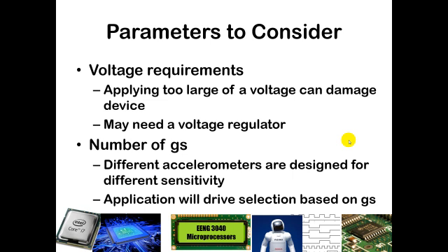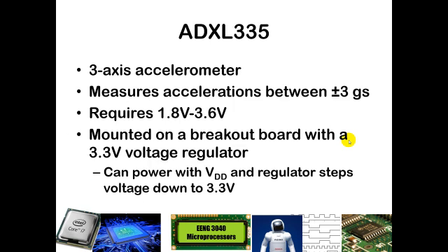If you are just trying to put an accelerometer into a tablet and may just reorient it, or perhaps you're trying to measure steps in a step counter, you don't need very high G ratings in order to do that. And so the application will determine how many G's we might need when choosing an accelerometer. We will use 2 different accelerometers in this course.